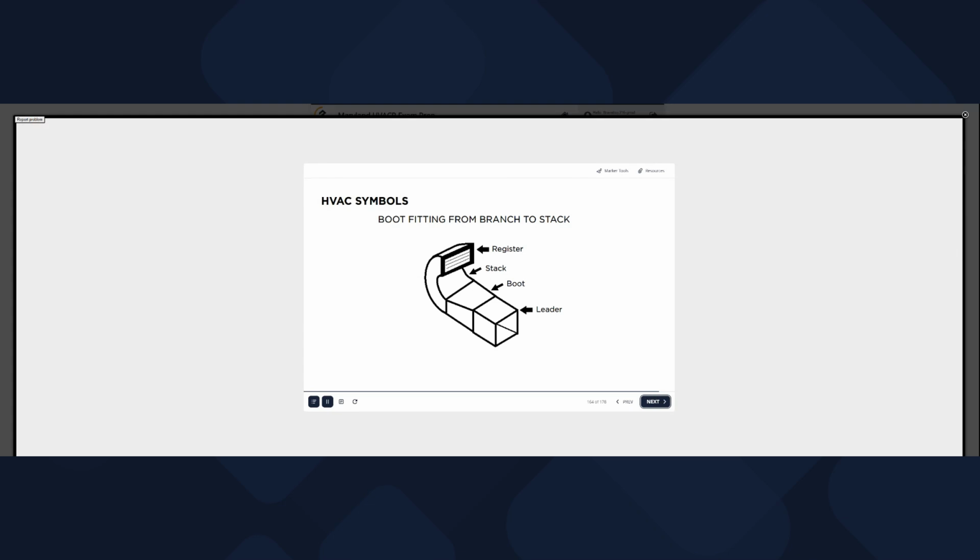An air register has the capability of adjusting the airflow by opening and closing a damper or flaps. Registers cover a hole in the wall, floor, or ceiling where the air duct enters the room. A combination of stack boots and heads makes up the basic structure of ductwork. Stack boot is the professional term for vertical duct, which, as the name suggests, helps airflow vertically. Boots deliver conditioned air into living space and house the register.